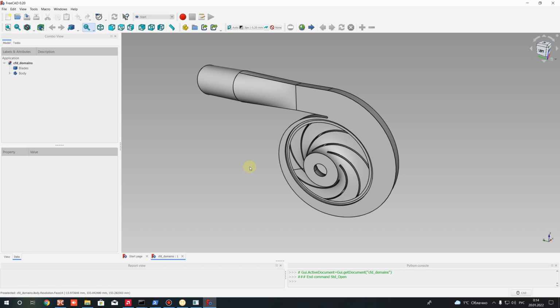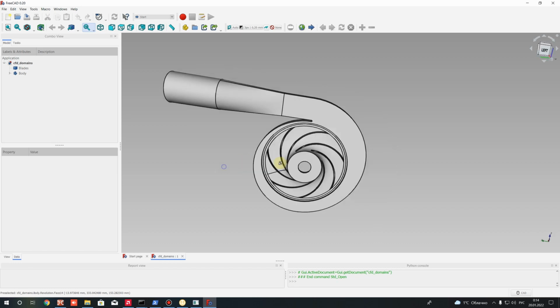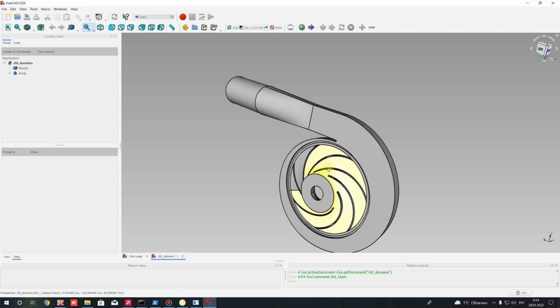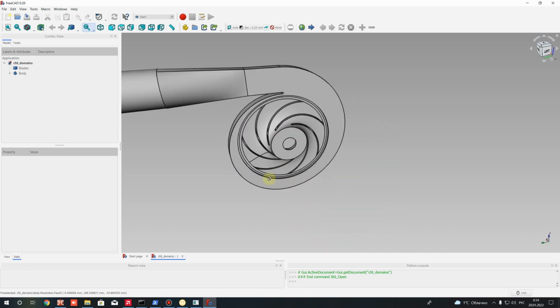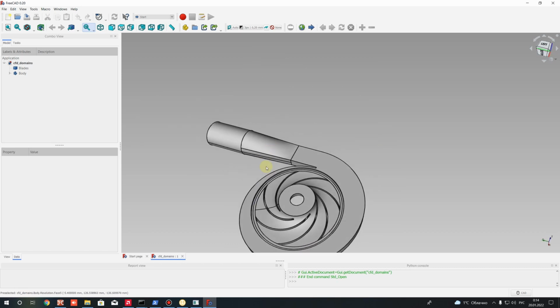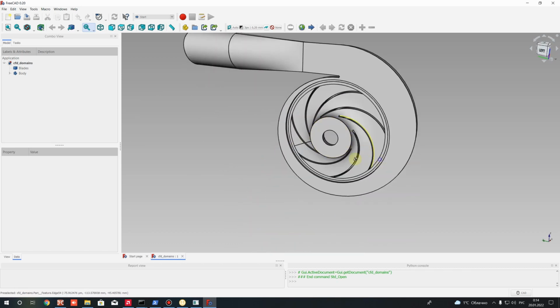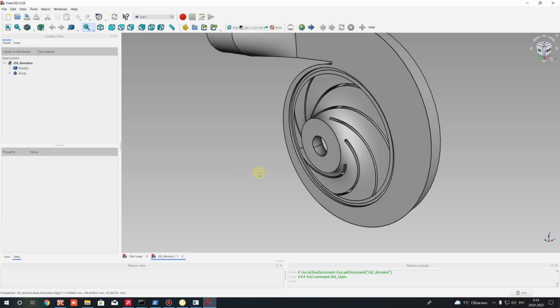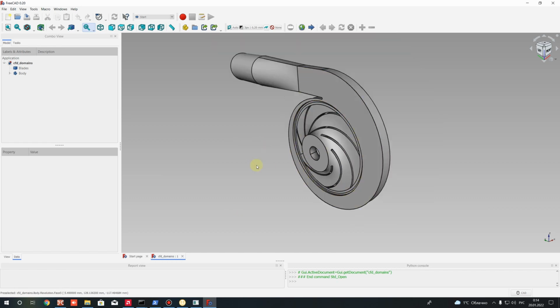Okay, in the previous video tutorial we designed the volute for your impeller, and we created the CFD domain for CFD simulation. Today we prepare one more, the inlet CFD domain for the impeller, and we save it to a step file, and we will use this step file for creation of a mesh in Salome Software.